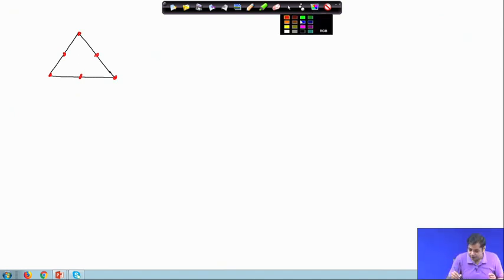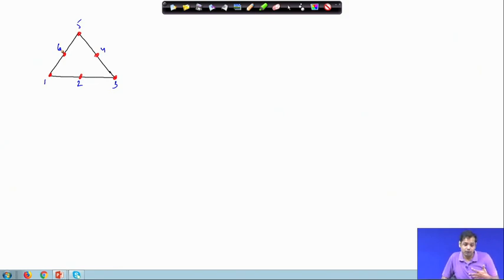Okay. So, again you have node numbers, for instance, suppose this is 1, 2, 3 and then 4, 5, 6. We already have seen how you number the nodes in the context of one dimensional problem. Depending on that, you get the population of the stiffness matrix, right. You can number those nodes in such a way that you get a banded stiffness matrix, and a banded stiffness matrix is always better to have from the computational perspective. Now, these are the node numbers.